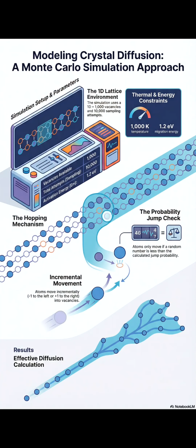Yes. But in 3D, the vacancy has way more options. After you swap with it, that vacancy might jump up or down or forward. It can literally escape from you. Leaving me stranded in my new position. Which is actually a good thing for diffusion, because the vacancy escapes. It allows you to eventually make a fresh move with a different vacancy that wanders by, instead of just bouncing back and forth with the same one.